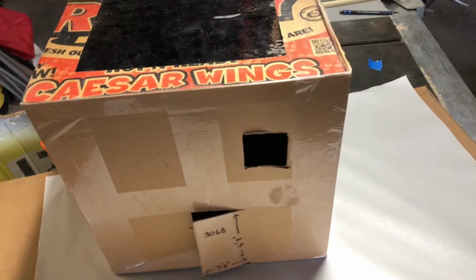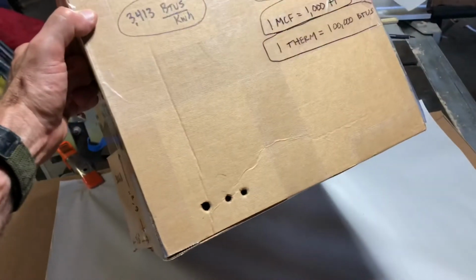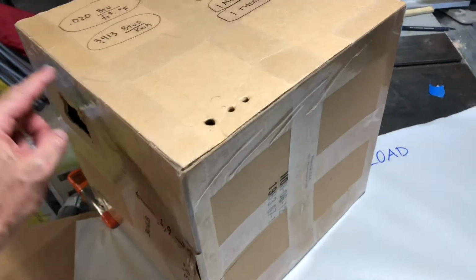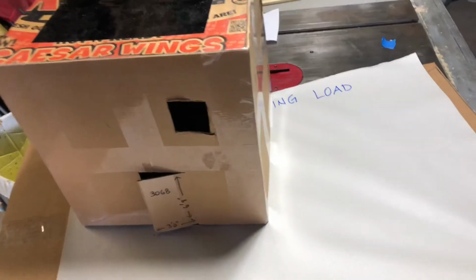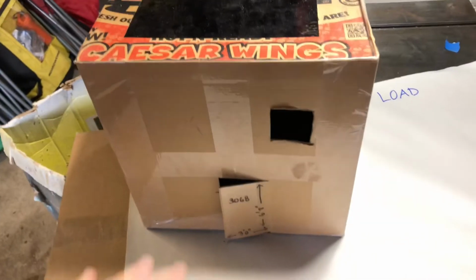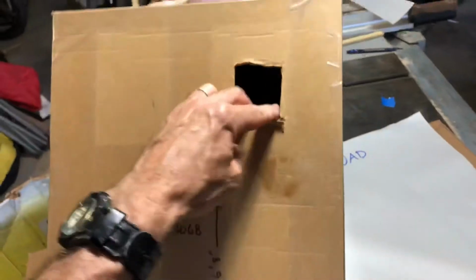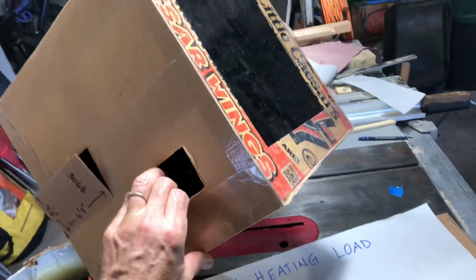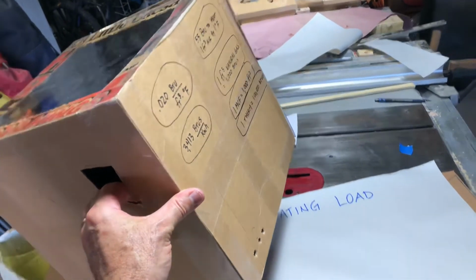QA is heat loss to air infiltration or exfiltration. Around doors, around windows, around those holes where utilities go. Wherever walls join each other and they're not airtight. So that's QA. So when we talk about transmission, you got to keep in mind we're talking about surface area. When we talk about QA, we're talking about volume. Remember, this is a cubic foot of air. We could have thousands of these per minute leaking in and out of our house. That is not unusual. All right, so let's look at design heat load.